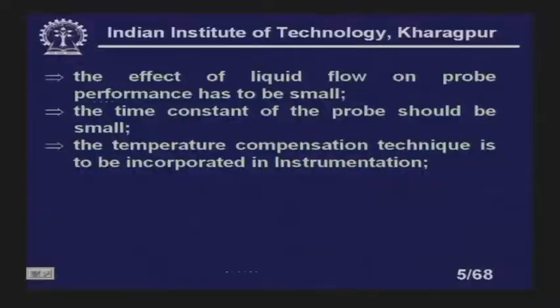Usually, in bioreactors, we are not much concerned with this. In most bioreaction cases, you will find the time constant is typically large. Suppose a reaction is going on for 72 hours, or 48 hours. Even if you sample each sensor's output every 10 minutes, that is considered quite high, because reactions take a long time and do not change so rapidly that you have to sample every minute.